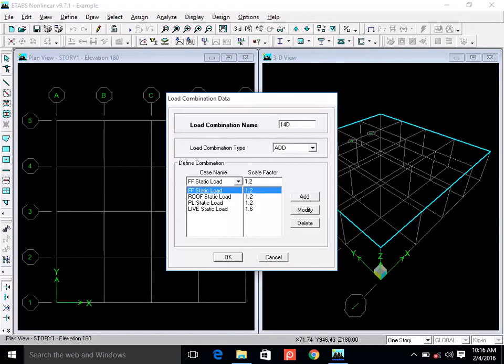Is it something other than scale factor? Yes. Okay, that is related to dynamic analysis, mode. Don't worry about it. Right now we are doing static analysis. When you do the dynamic analysis for moving loads, or I should say time dependent loads like earthquake and wind, then the modes come into picture. So for static load analysis you don't have to worry about modes.